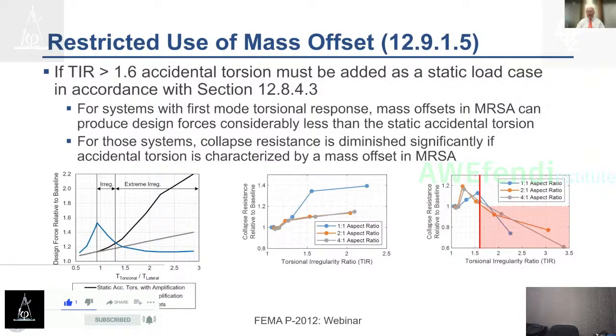There is an interesting finding from the project. We found that using one method that you might think is precise would help makes the problem worse. The big idea with accidental torsion is that we can't predict perfectly how our system is laid out. So there could be some twisting in a system that is nominally doubly symmetric. It could still twist. And so the long used code rule is that we need to consider a 5% offset of the lateral force from the center of mass.